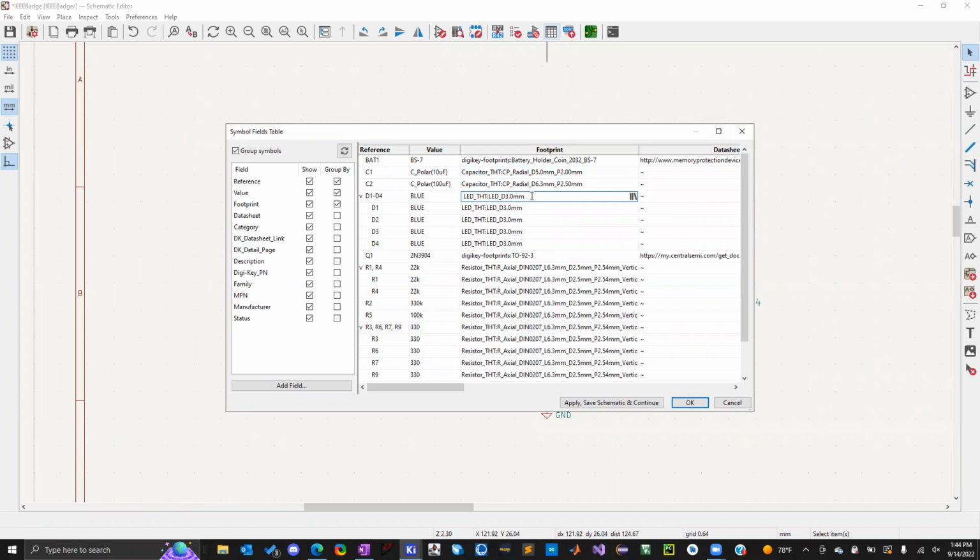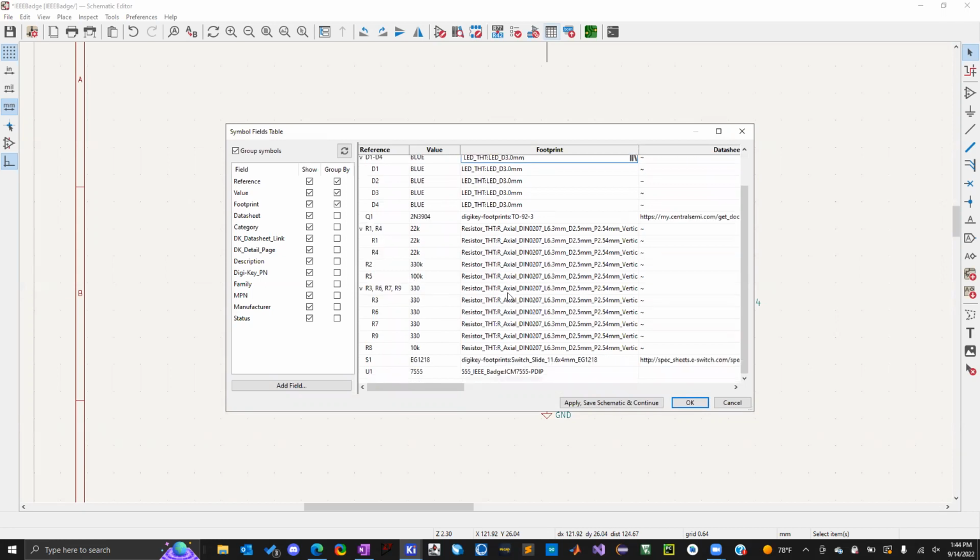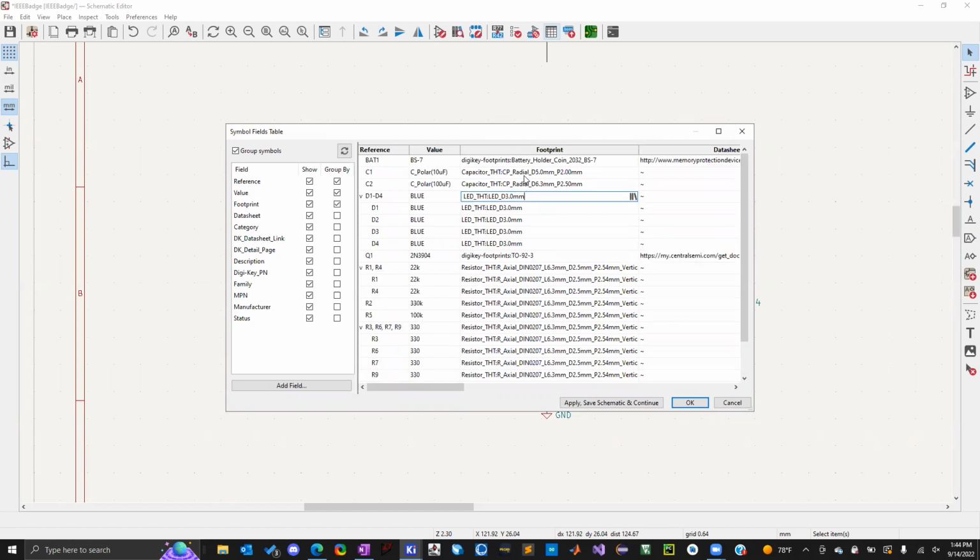They end at the connection part to the resistor, but since you can draw a straight line through the axis of the resistor, they're called axial components. Whereas with capacitors, if you've seen electrolytic capacitors, they're cylindrical and they have the pins on the same side. They refer to those as radial. So keep that in mind while you're picking your components.